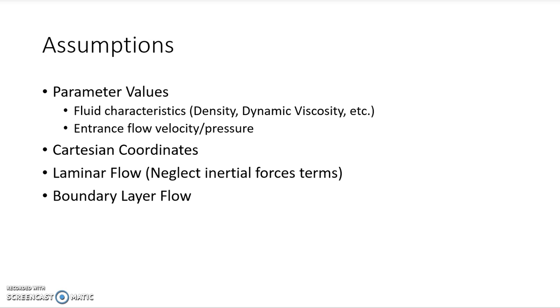Another basic defining assumption has been in the use of Cartesian coordinates. The use of laminar flow was assumed and tested in some model iterations. Boundary layer flow is also assumed with the top portion of the model as a slipping wall. The slipping wall is therefore the free flow velocity, just above the boundary layer.